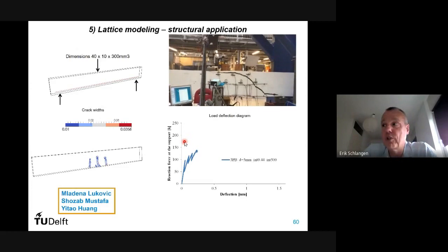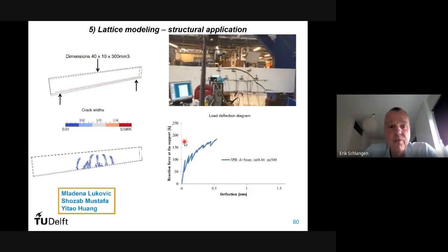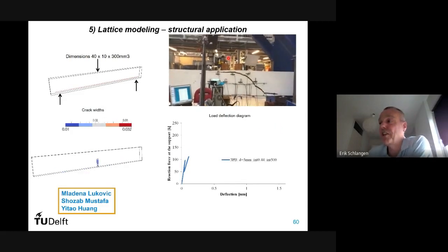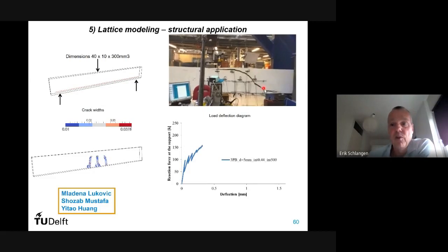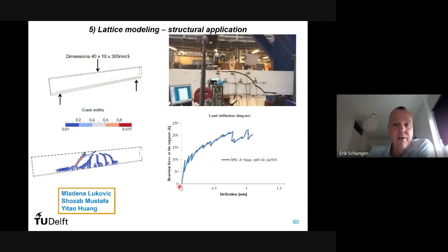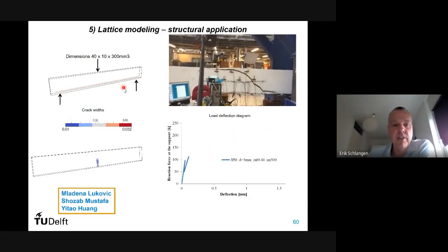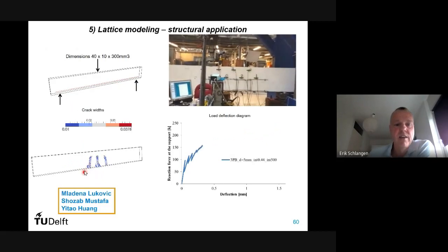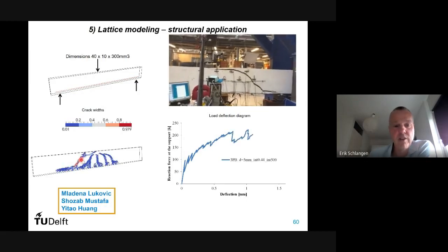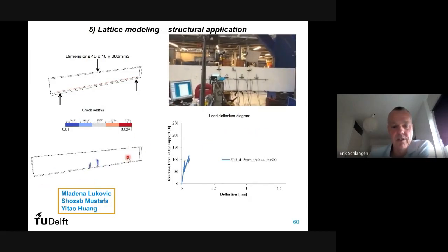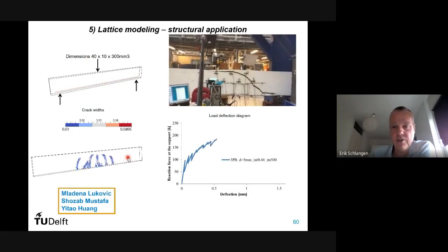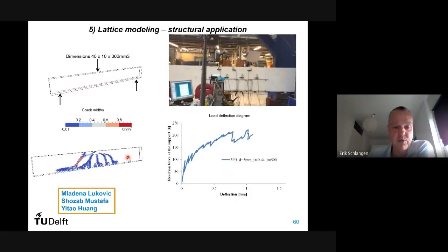fibers? She also scaled up this model to simulate this kind of fracture in beams, so reinforced beams. You could call this a shear crack. I just call it a tensile crack. But if you do the simulation with reinforcement in it, you see that if you first have bending, your cracks will start, and then one of these cracks will open up. You can call that a shear crack, but it's just, I would say, because the tensile stresses rotate and your